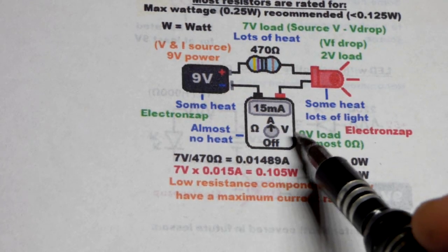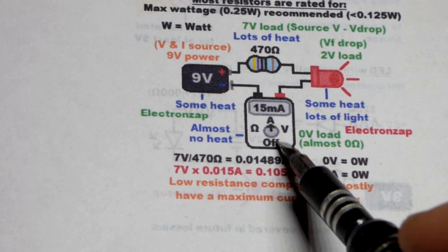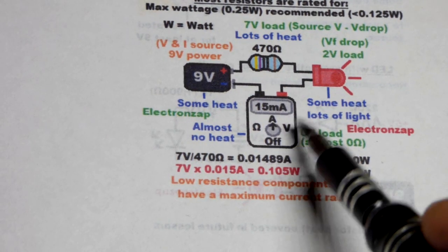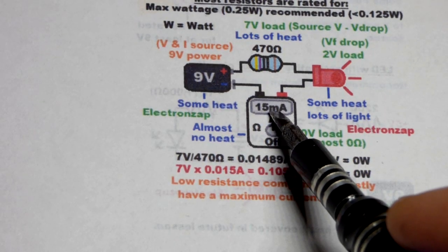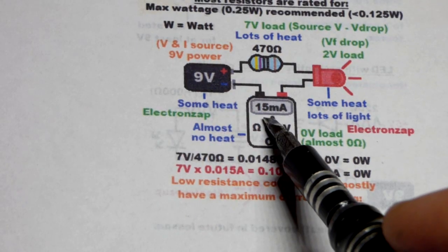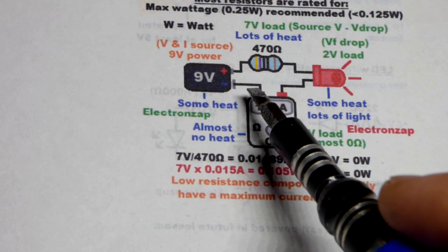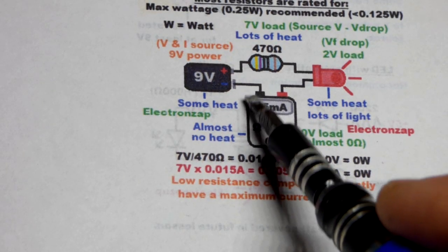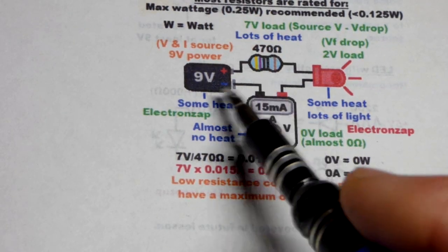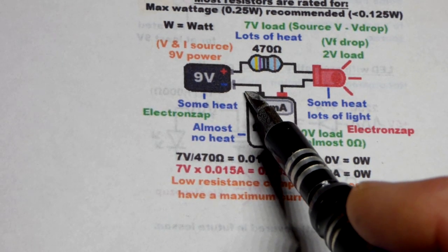But definitely you want a multimeter that can measure voltage, current, and resistance. Usually they've got a whole bunch more. And auto ranging is the most simple. You would just set it to milliamps there instead of amps. But in any case, this is just a simple drawing. So we got that 15 milliamps. Current has to flow through the meter in order for it to measure it right there. There's other ones where you've got a little clamp or something. I don't have any. You could clamp the wire, and usually they're used for higher current, and they can sense the magnetic field, how big that is or however they do it, and get a reading there.